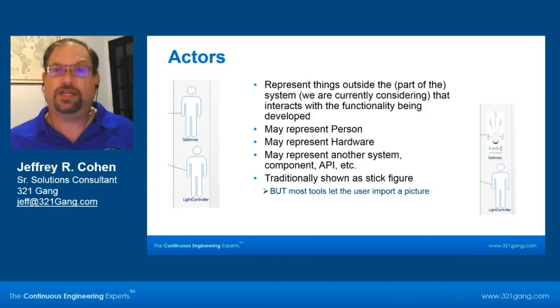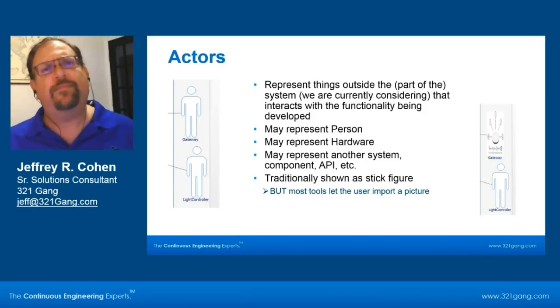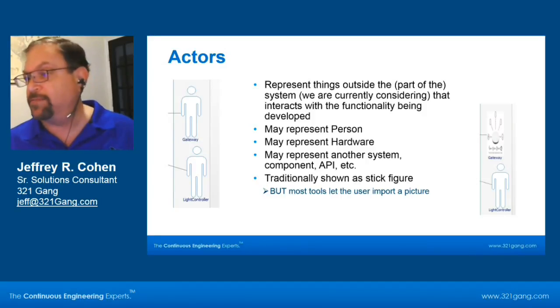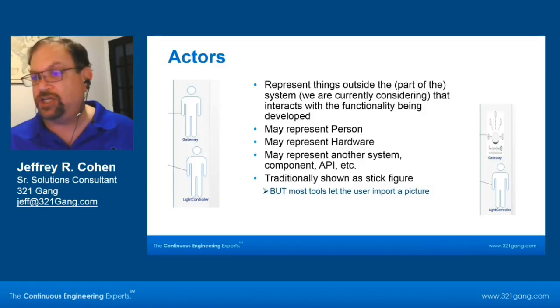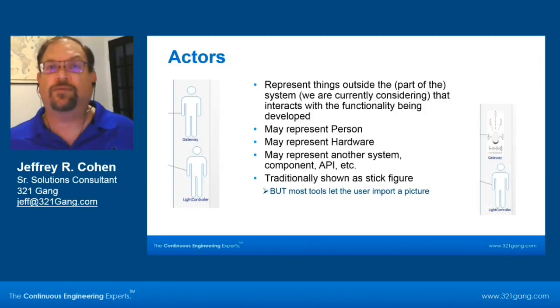They're traditionally shown as stick figures, which is fine when you're dealing with other systems engineers or other software people, but sometimes it's confusing to people who are not technically based or not familiar with the domain. Fortunately, most of the tools will allow you to replace the actor with an image that represents that actor. So in this case, I've got the gateway, and I showed it initially as a stick figure. Over here, I replaced that with a JPEG image of what the actor looks like. For anything that you're going to be putting out to higher level people, definitely do this.